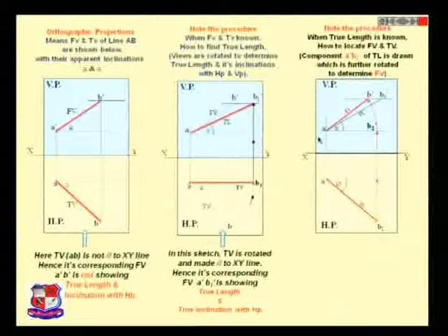Now we will extend the front view itself till the B2 parallel line. Always the front view and the top view would be in the same line only. So what I have done, I have just dropped down the shadow of the front view like this till the B2 point.